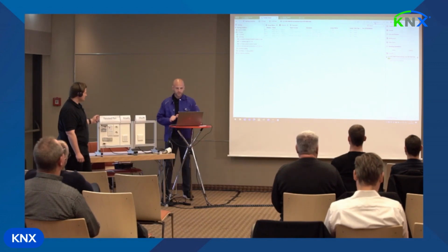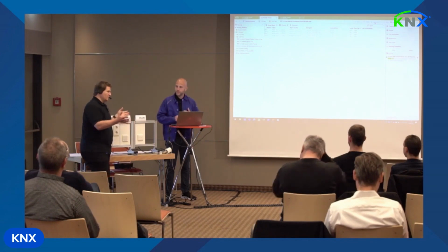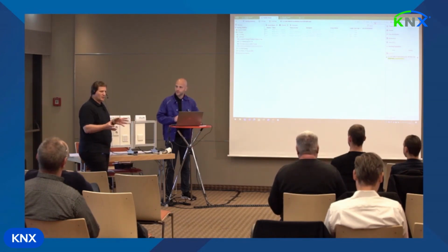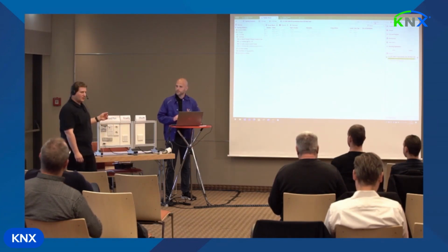While this is downloading, what additional functionality do I have now when this is finished? When you integrate a multi-device into an installation that is configured as RF ready installation, the multi-device falls back to ready mode during runtime. So while it's working, sending out group addresses and frames on RF, it's acting as a ready device. The only addition that you have is the enabled security for the protection against configuration. So the download of the device is done with secure telegrams, and afterwards the device is locked. So without ETS knowing the keys to access the device, you cannot reprogram this device.